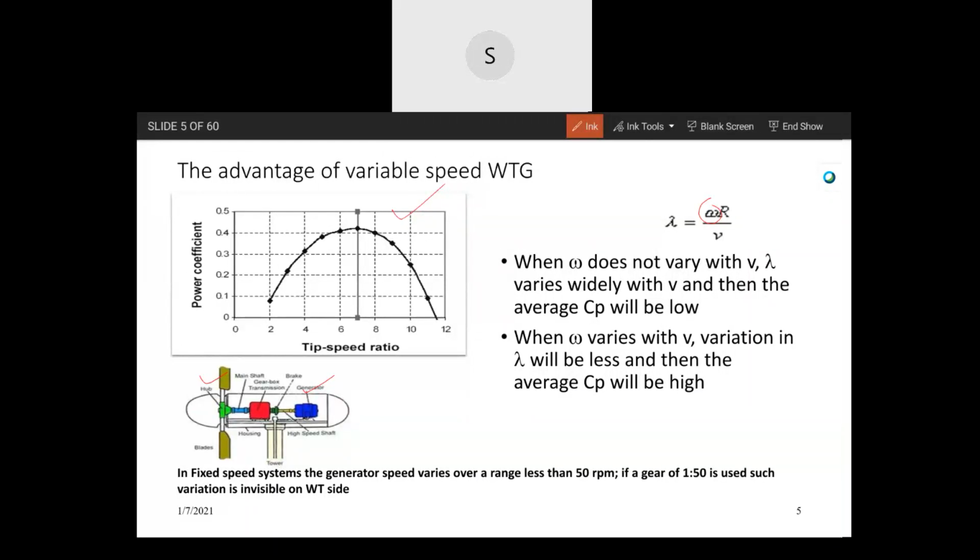So that means for every wind speed, the system will decide at what speed it has to operate so that power balancing is secure. Shall I repeat? For every wind speed, the two machines together decide. It is like simulating through iteration. These iterations are happening in every system for power flow equilibrium. The generator decides the speed that it requires, and that change is hardly 3 to 5%. So the turbine speed cannot be different. There also the speed change will be 5 to 3%.